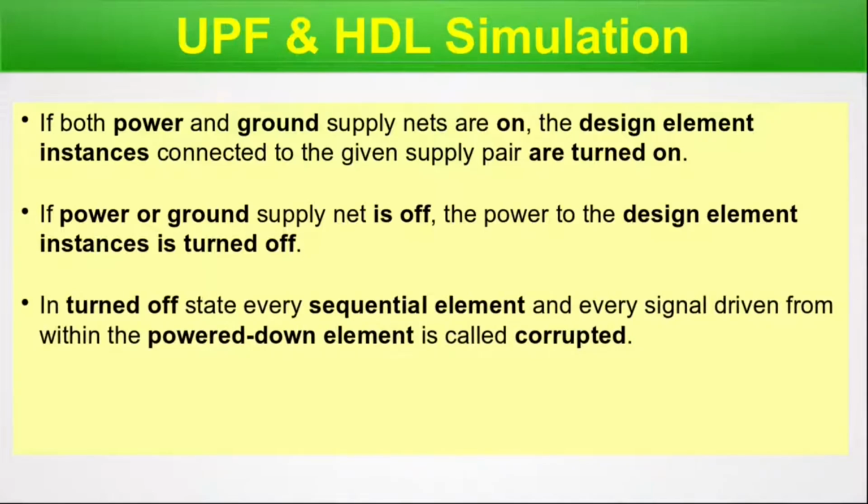In turned on state, every sequential element and every signal driven from within the power down element is called corrupted because this block is totally off. So any signal going out is unacceptable.